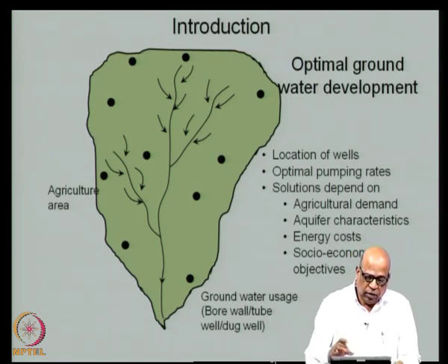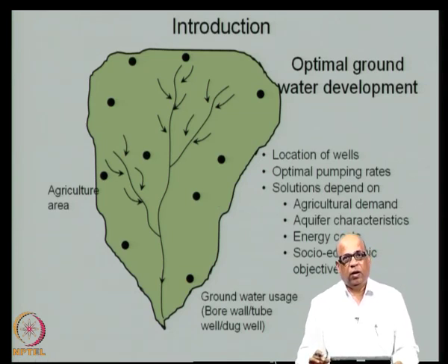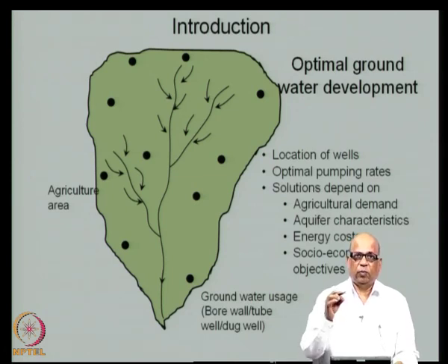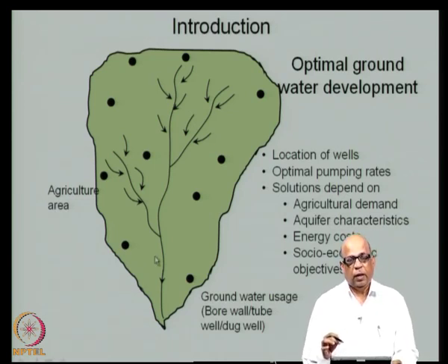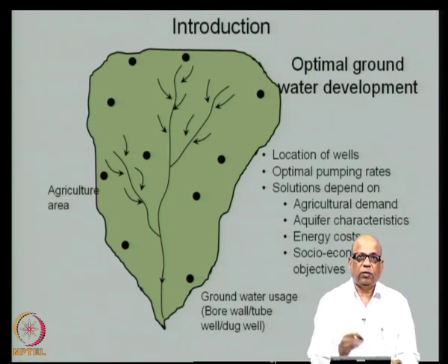Now, all of these we should be able to put together and then make decisions on where to put these groundwater usage points, knowing the surface water hydrology as well as the aquifer characteristics, and knowing the groundwater hydrology, how the groundwater levels fluctuate with respect to the usage as well as with respect to the rainfall input as well as the irrigation input and so on. So, we synthesize and integrate all of this information and then arrive at decisions on how much to use of the groundwater and how much to use of the surface water, when there are no storage reservoirs here.